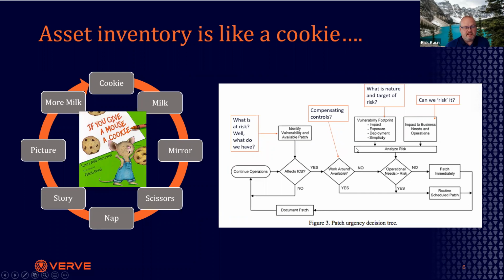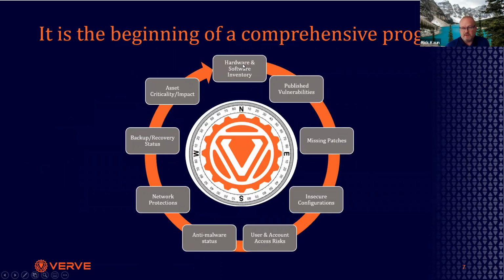So what does this mean for us in OT? It means we need to not just understand inventory. We need to go far beyond inventory, from inventory to vulnerabilities to patches available for those vulnerabilities. And it sure wouldn't hurt if we could take the full list of patches and sub-filter that to vendor approved. Beyond that, we probably want to know how the devices are configured, so we can pull other levers rather than patching, which is often desired or the only optional path. That gets us into things like, do we know the users? If I'm trying to compensate for BlueKeep without applying the patch, I'd like to be able to disable remote desktop and the guest account if I can.